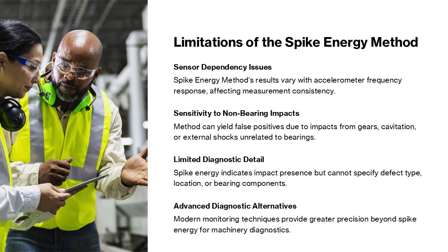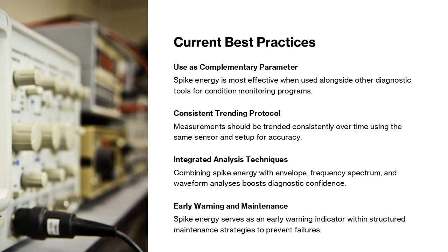As machinery and monitoring technology have advanced, more sophisticated techniques have become available that offer greater diagnostic precision. Understanding these limitations helps engineers apply spike energy appropriately and avoid over-reliance on a single parameter. In modern condition monitoring programs, spike energy is best used as a complementary trending parameter rather than a standalone diagnostic tool.